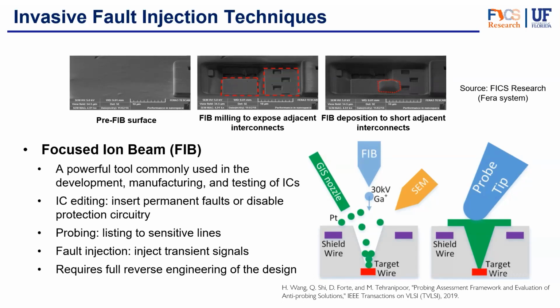At the same time, an attacker can use these FIB technologies to insert some traceable paths from the very last metal layer to internal signals in the design. This gives them exposure to internal signals, some of which may carry critical operations and critical information, such as assets in the design. And so they need a physical change in the chip.